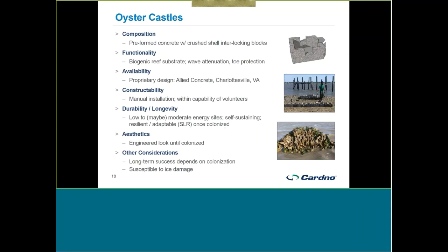Working within the intertidal zone, we don't see a lot of persistent oyster reefs. So this is something that may be more in the subtidal zone. It may be out in front of a living shoreline that's constructed with other techniques. So it's a component that's intended for both reef building as well as maybe some energy dissipation, causing a wave to break a little bit sooner, so that when it does encounter your living shoreline, it already has a little bit of that energy knocked off.